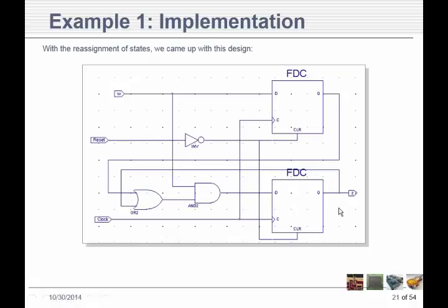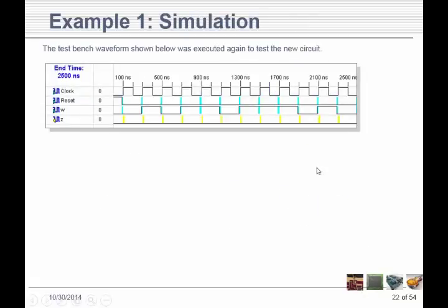You don't have to always put those numbers in sequence. If you had, let's say, 15 states, then you've got to use 4 flip-flops. Or let's say it's 9 states. You've got 4 flip-flops, right? You got to do it. No, even 8, you have to have 4 flip-flops. But you got a lot of states there that aren't being used, and you can move them around anywhere in there. You can define them however you want. And that's one thing I do like about this.